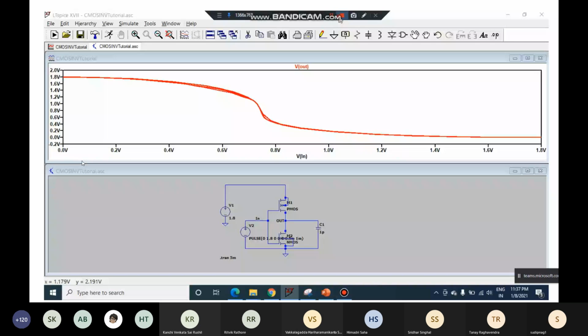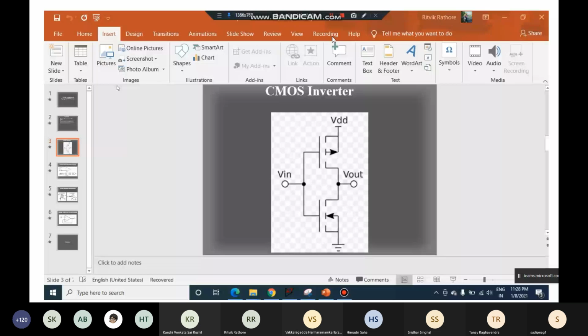So you have to play with the W such that you can actually work on different current levels or biasing conditions, or even handle the intermediate node voltages, and also the branch currents you can control by changing the sizing. As a result, the overall characteristics or overall performance of your circuit will change. Okay, so that is something about the CMOS inverter.